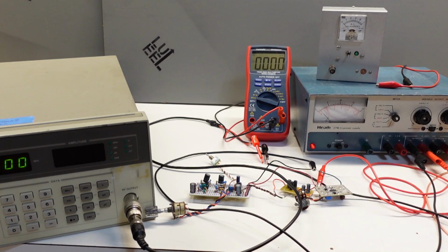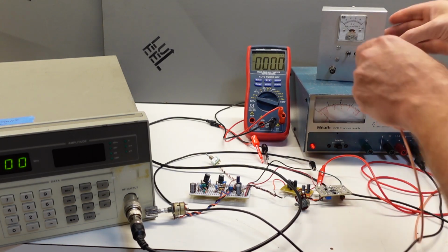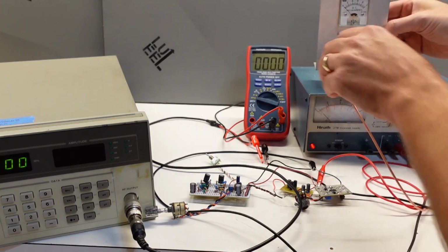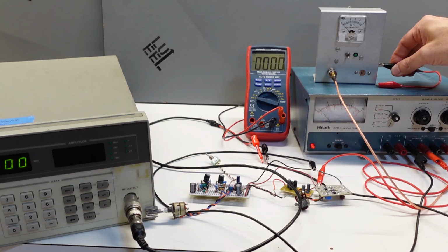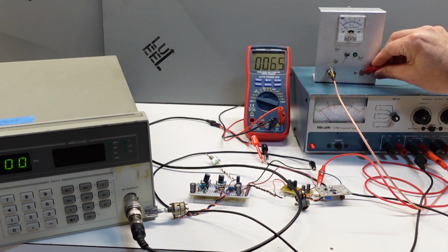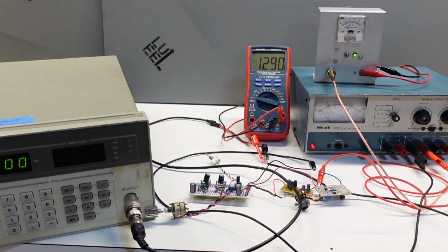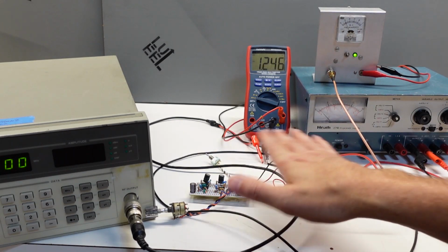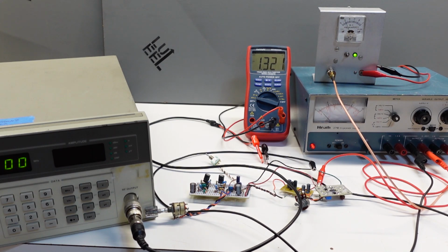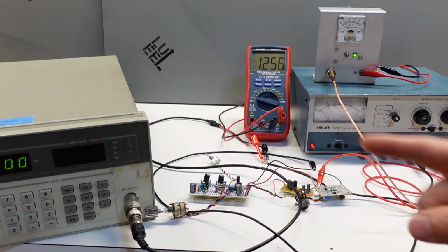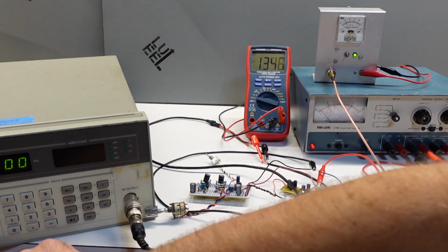So I've reconfigured the coax connection here just to go directly to the meter. It's got its own 50 ohm load on the inside. So I'll hook up the DMM to the feed-through cap. Of course, I've got to turn the meter on, and there's going to be some base reading in there. That's just noise. You know, clearly I don't have this well shielded. In fact, it's not shielded at all around this area, so I'm going to be picking up some noise. But for the magnitude of the reading I'm making, the noise really doesn't matter. So then the next thing I do, I'll turn on the RF signal and see what reading we get.